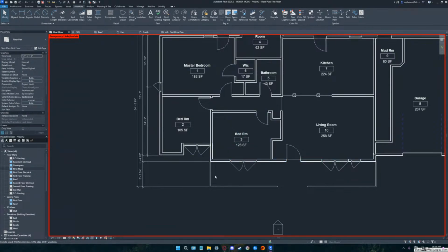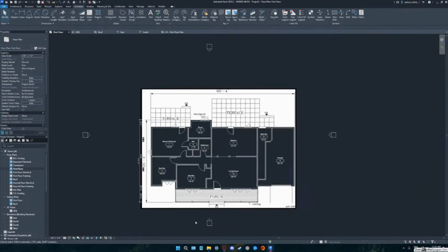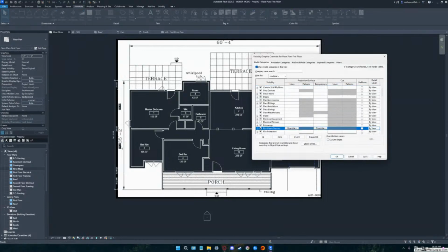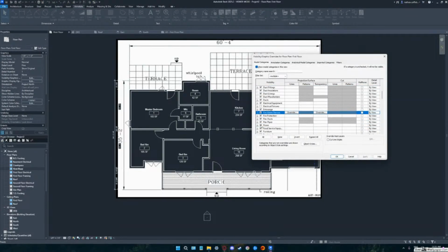If you unhide your image and make it transparent, so you actually, we're going to do something even different. So the reason that you made the view transparent was because you could no longer see your image, right? Yeah. And the reason you can't see your image is because you drew a floor, and that floor is hiding everything that's below it. So remember your VV command? Go down to floors. And I know, nope, that was a good idea, but don't do that.